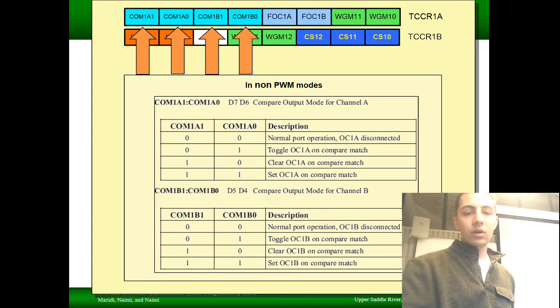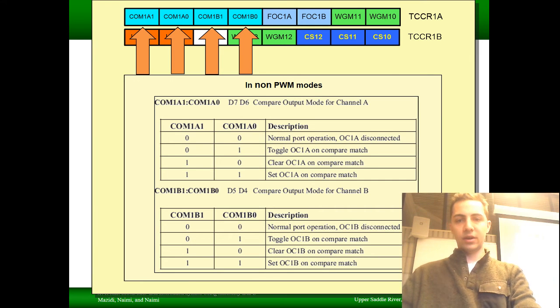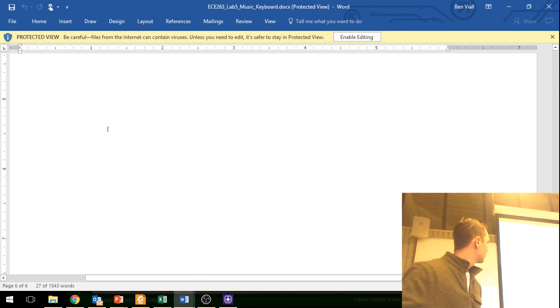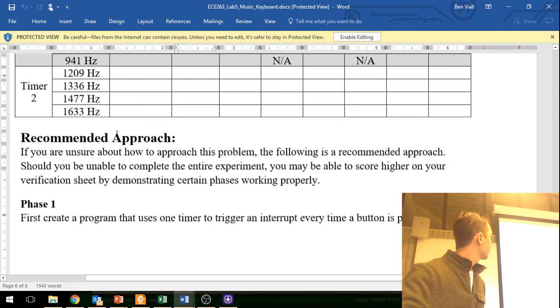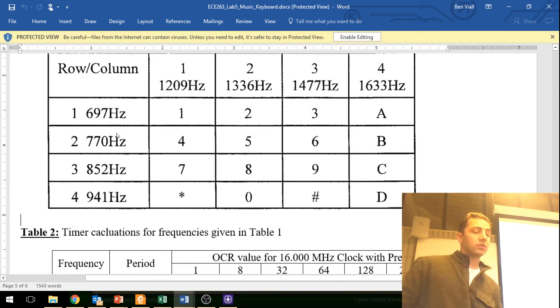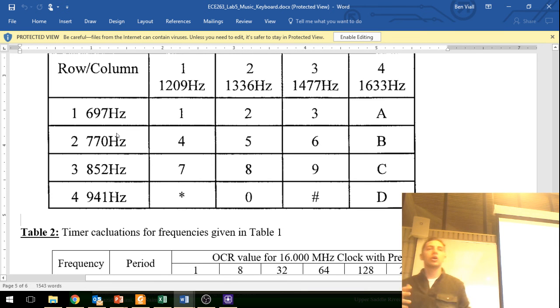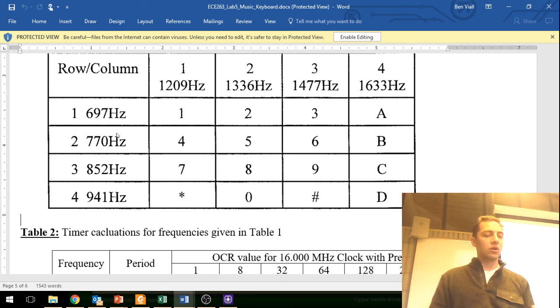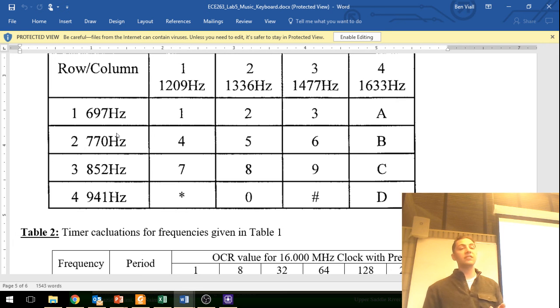Now, where is the table that we're working from, page up, is this table. Now, if you look in your book, there are code examples that will actually give you the character values for all of these things. It might be interesting to set up your UART to send these characters over as an additional debugging method. So every time you receive a key press, send that character over the UART. It's not required for the lab, but might be really helpful in debugging.